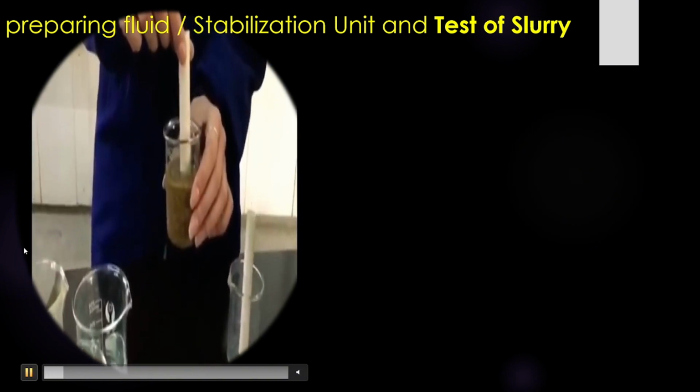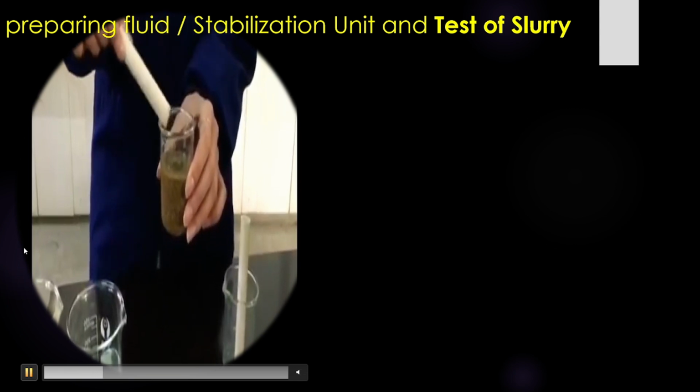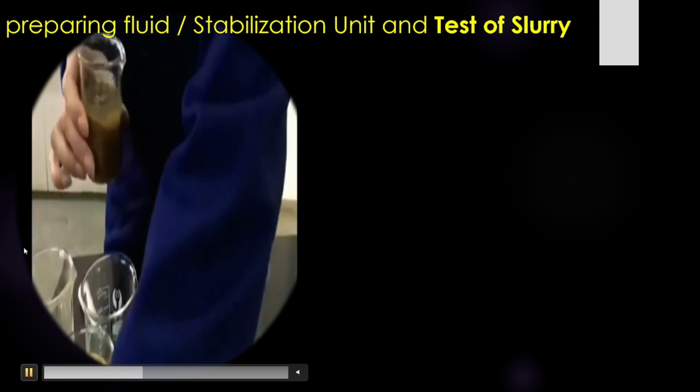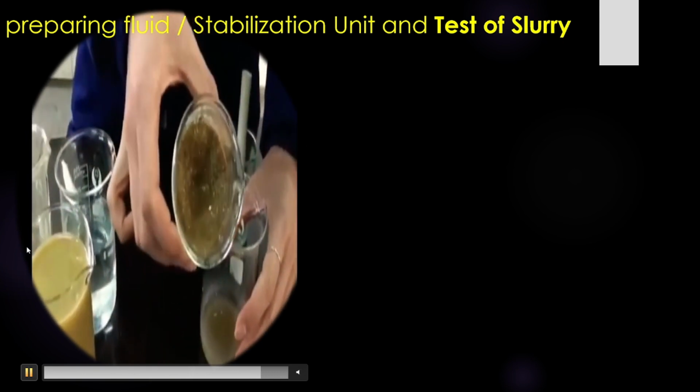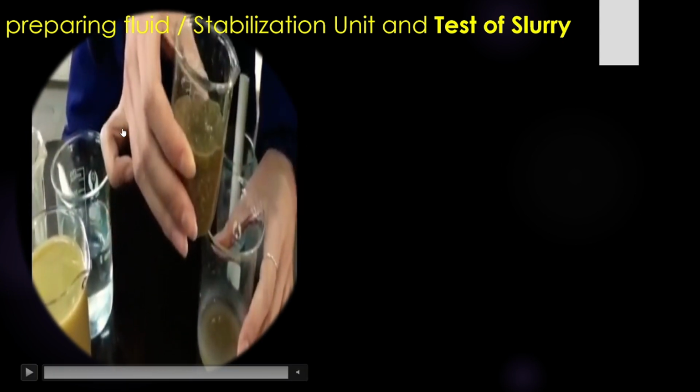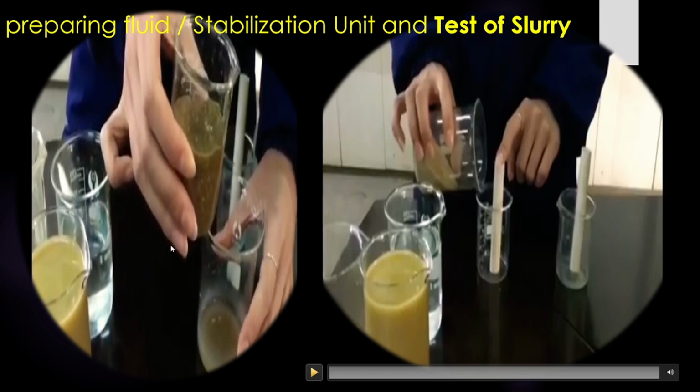The first one shows how the pile reacts without any slurry material. As you can see, this is a soil sample, and then we inserted our pile, and then we dewater, and we are going to see the hole. So what we are going to do is put reinforcement inside here, but as you can see in the figure, the soil already collapses or caves in, so we cannot get the bore excavated through the soil stratum here. So in the next video, we are going to use a slurry material.